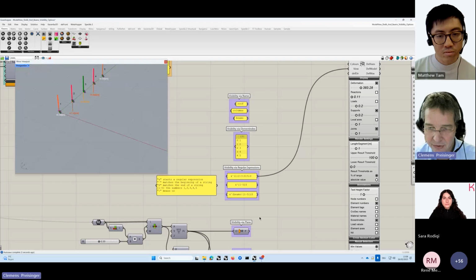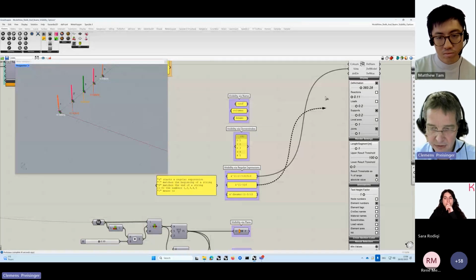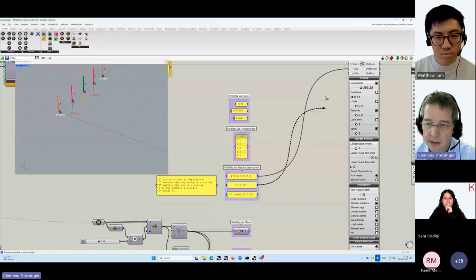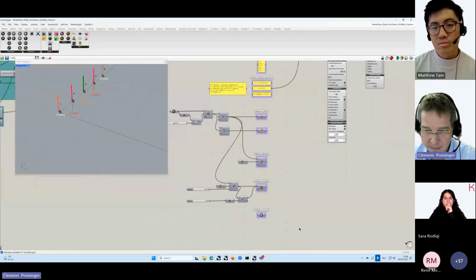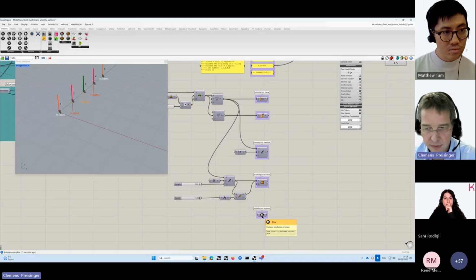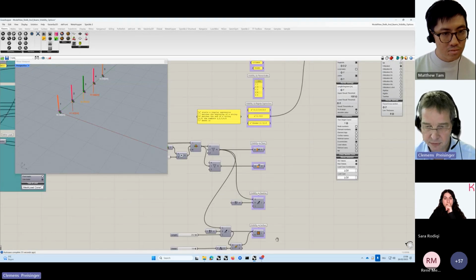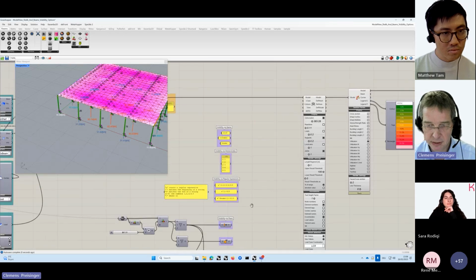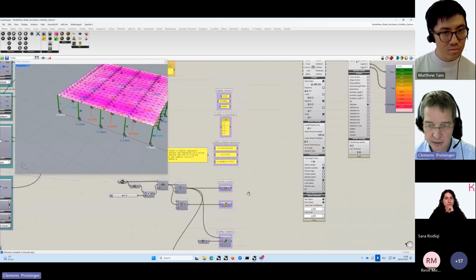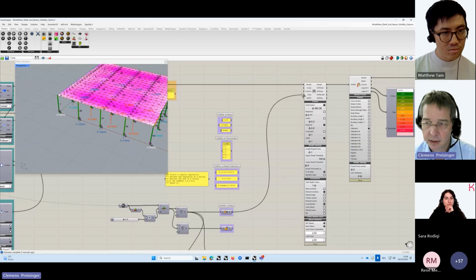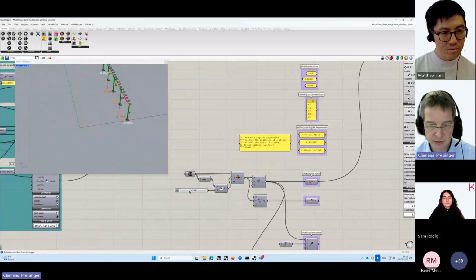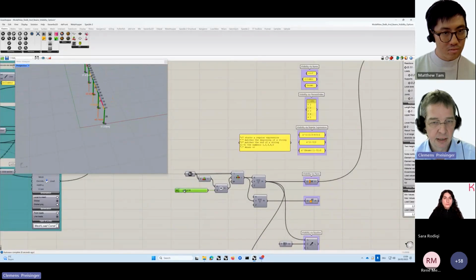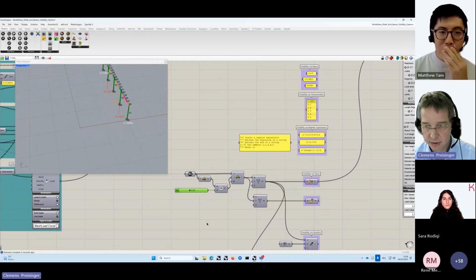So, or the same here. With these regular expressions, it's actually possible to do a very refined selection of the elements. And now what's new is that besides a closed volume, a BREP, which was already possible in the previous version, it's now also possible to supply, for example, a plane. In this case, a YC plane. And you see then all the elements which lie on this plane. So in this way, you can specify sections through the building and see the results only at specific sections.